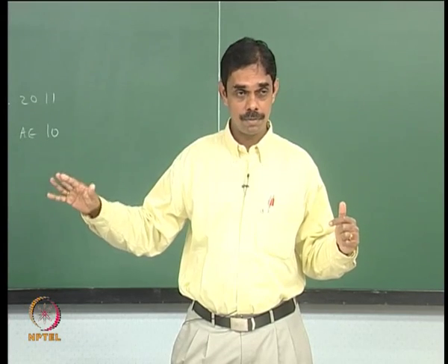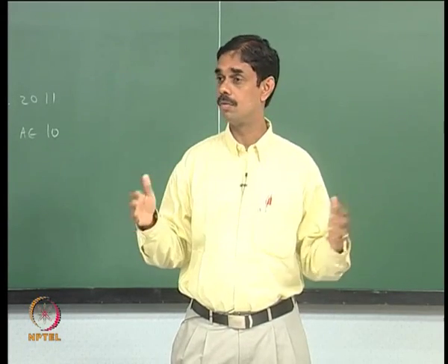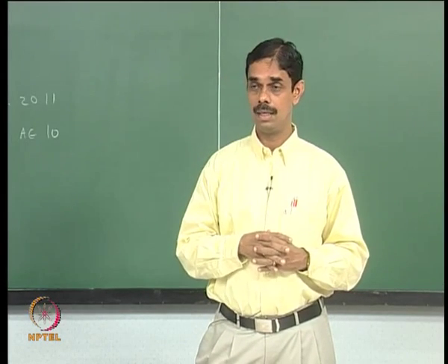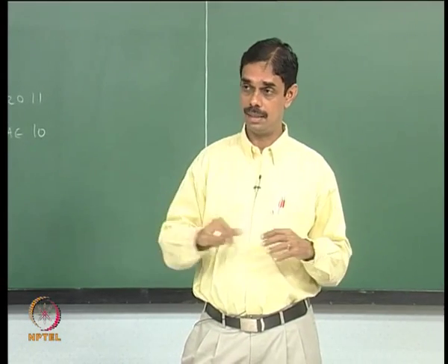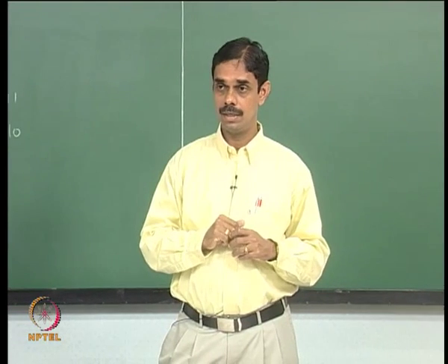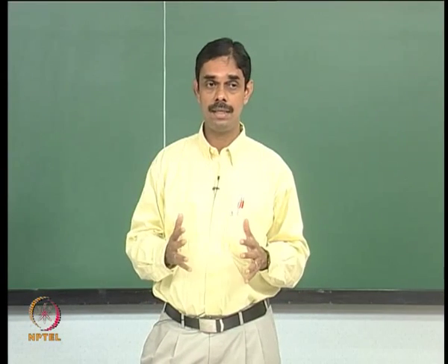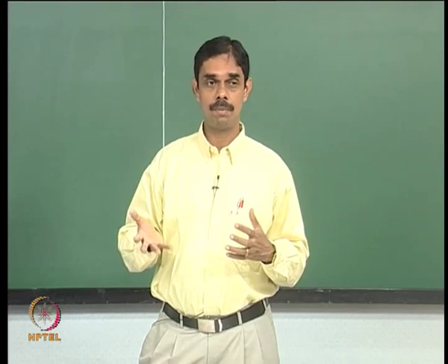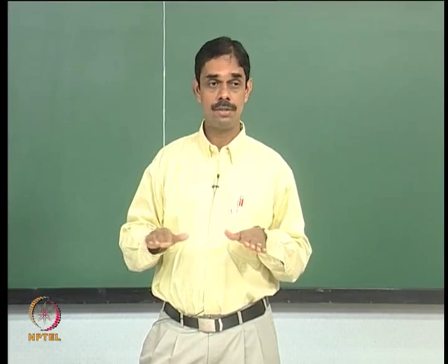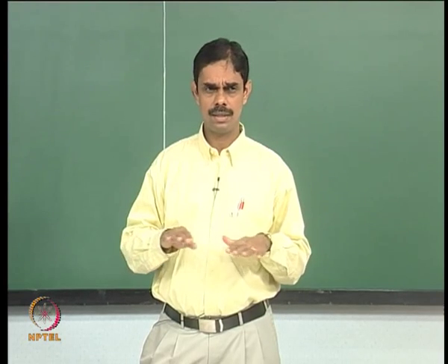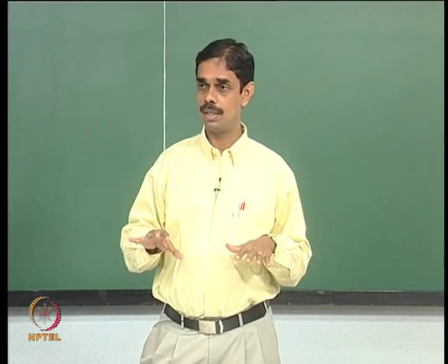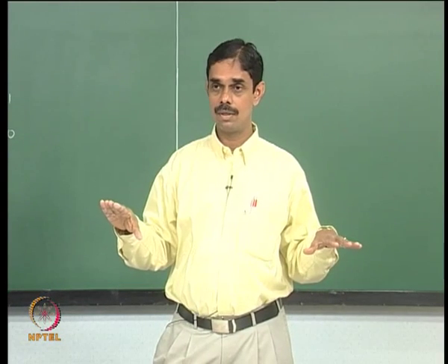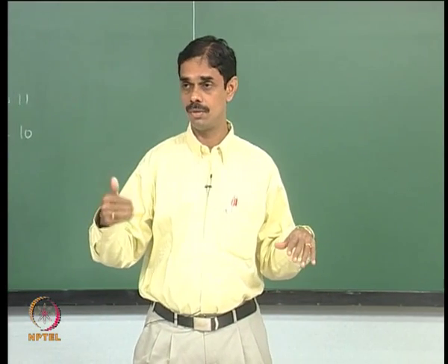In the beginning the amplitude will grow, and the growth will happen over half a second, one second or quarter second of that time scale, and then it will stay steady. Why will it stay steady? Because initially you are putting in power and there are some losses, but as you increase the power you lose more, and eventually you reach a situation where whatever you put in is equal to whatever is lost, and then you maintain steady amplitude. So that would mean there is no further growth or decay.